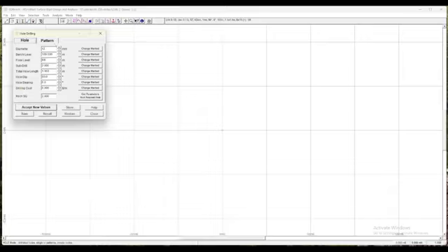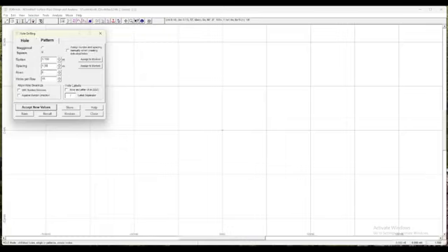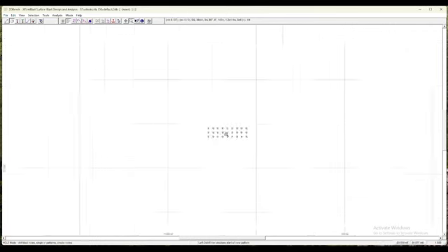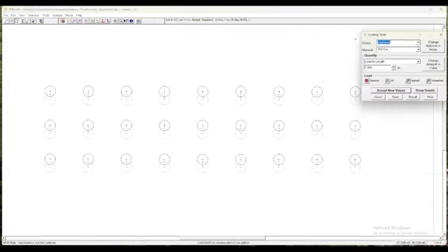Next, we used the JK SimBlast software, together with 2D Bench, to simulate and analyze our blasting designs. In this demonstration, we began by setting up the bench geometry, defining the height, free face, and burden line according to the site parameters. Then we entered the blast pattern, including hole spacing, diameter, and depth based on our design sheet. The software allowed us to input explosive details, such as ANFO and water gel quantities, delay sequence from 0 to 200 milliseconds, and staggered or square arrangements.